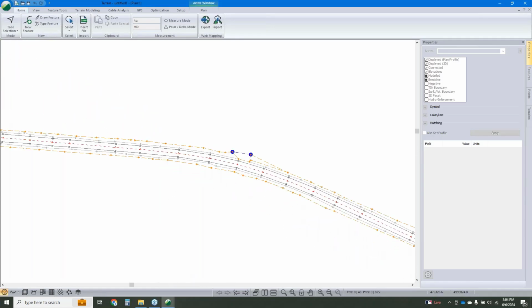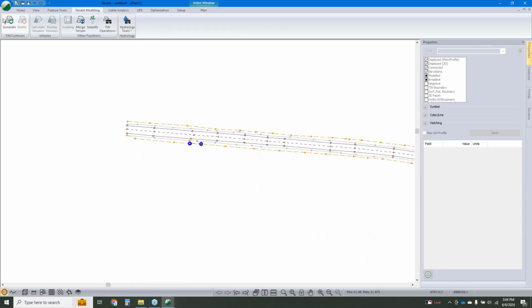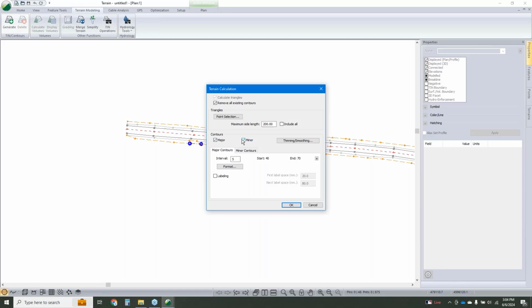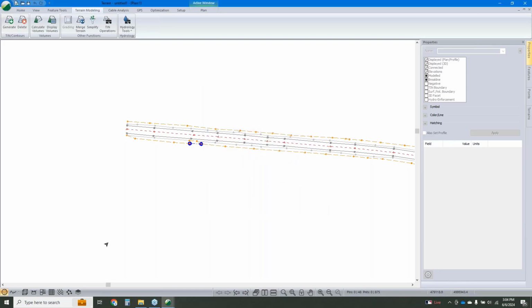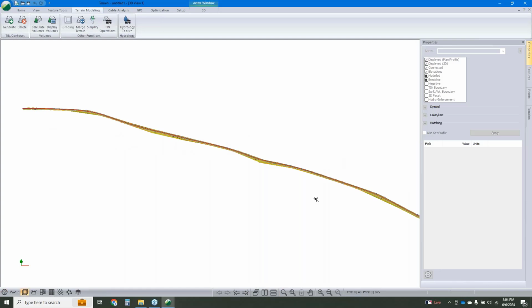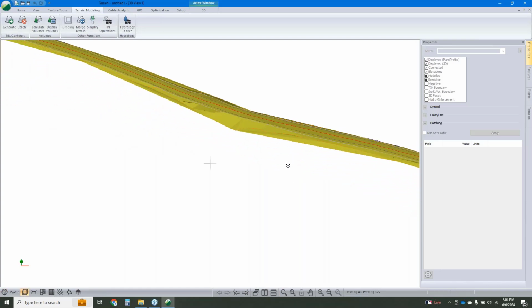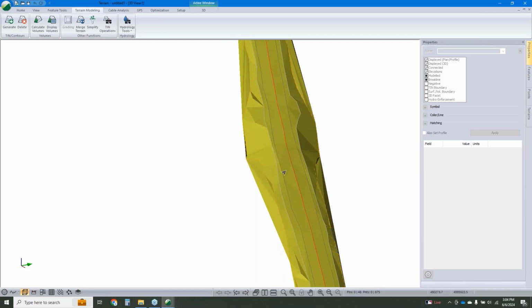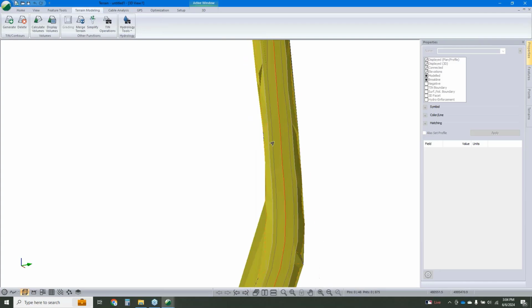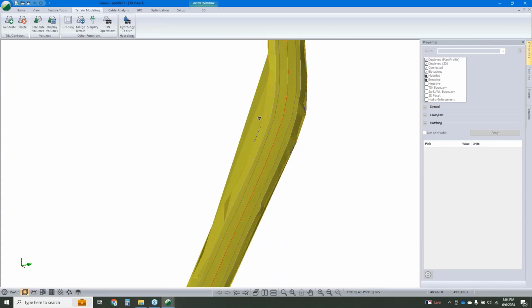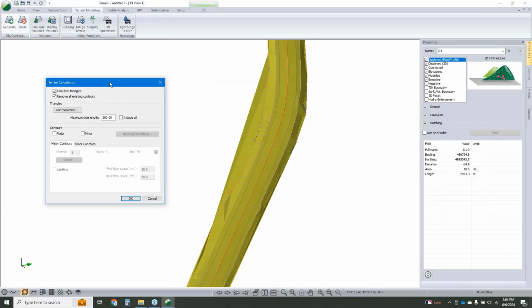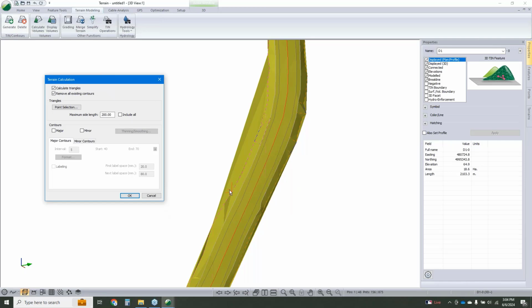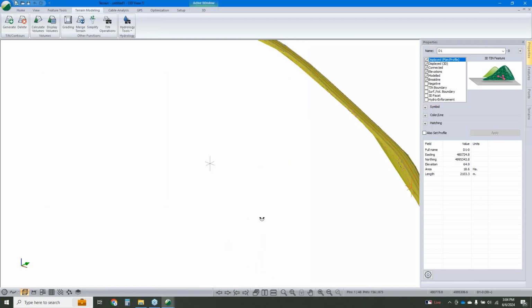And here I'm going to start by just modeling it by clicking the buttons here. But I'm going to talk about an extra step that's nice to consider when you're merging two data sets together. So with this, I see my surveyed center line, my edge of road, but I've got these long triangulations here that I don't necessarily want to include. So rather than controlling how far out my survey is interpolated here, based off maximum side length, I'm going to use a tin boundary feature.